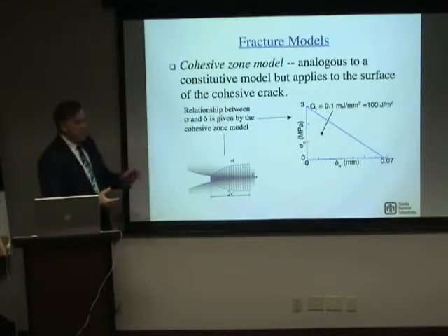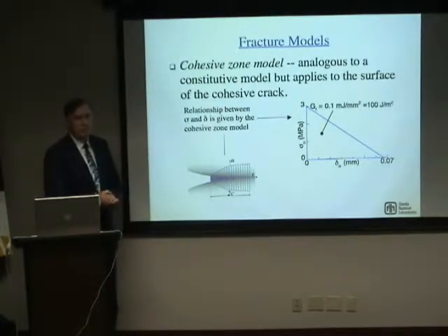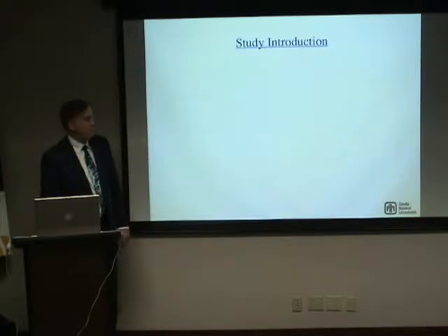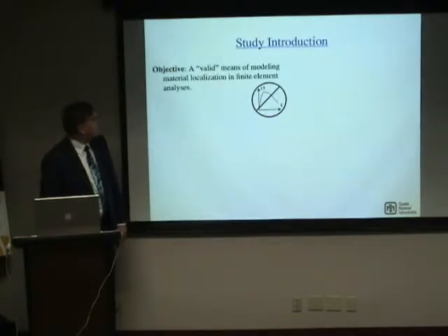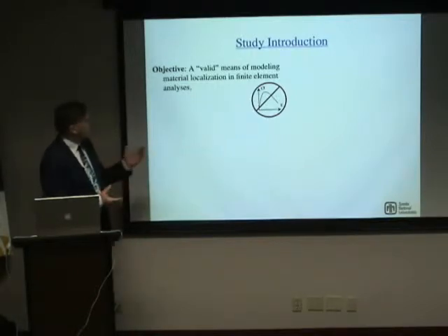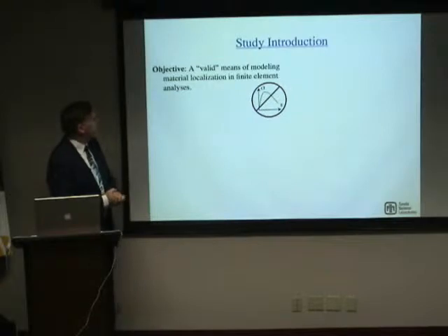So there's no more singularity. Right. In the type of models we're talking about, we don't have the singularity, and I'll come back to that in just a moment when we talk about the enrichment functions. As you're alluding to, in linear elastic fracture mechanics you do have that singularity in the stress near the tip. Our objective in this work originally, and I'll mention the history in a moment, is a valid means of modeling material localization in finite element analyses.